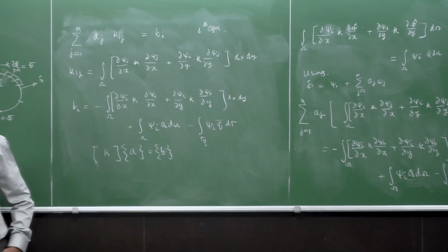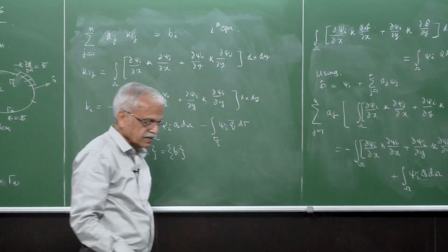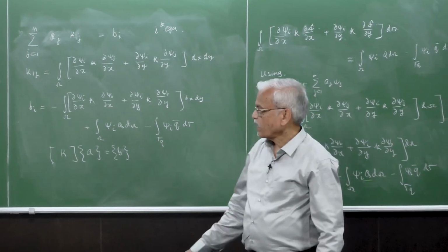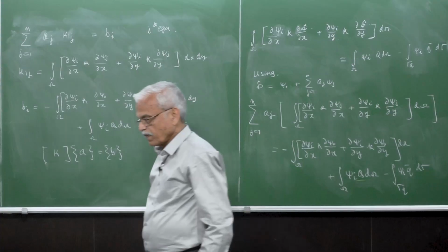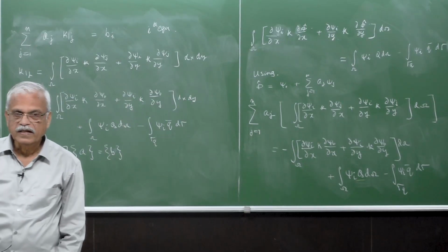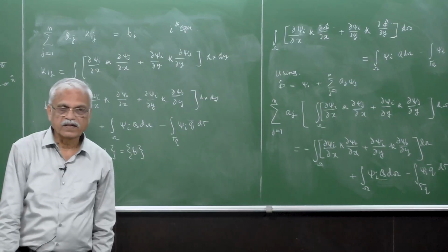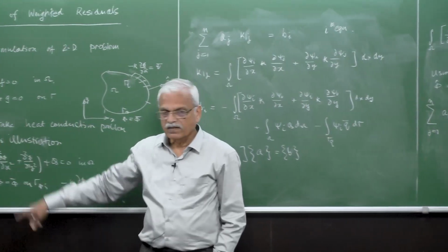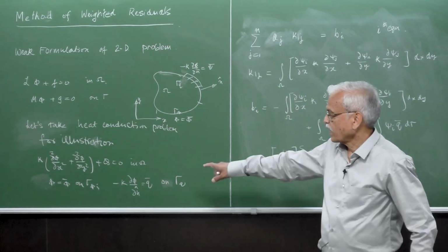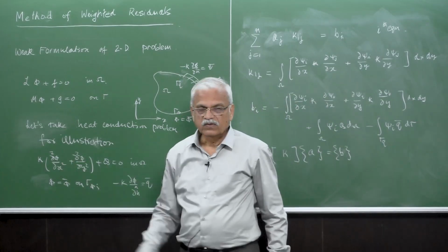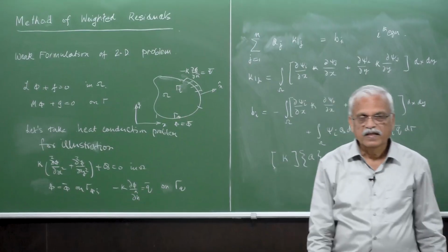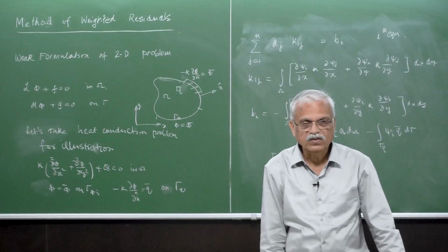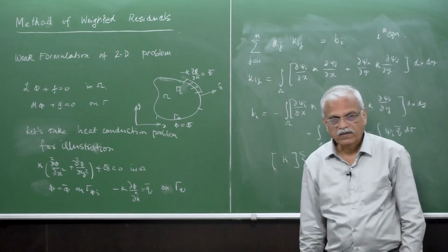Very interesting facts here. One is that this is a weak formulation, as I was telling in the last class, where the phi hat to start with only requires a lower order continuity condition. In the strong form, we had used L for phi hat. If L is a second order derivative, then the second derivative should exist, which we call C2 continuity.